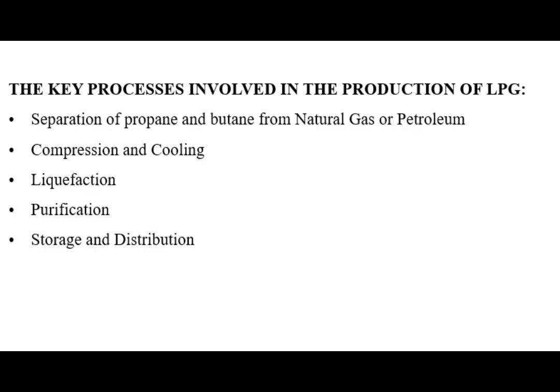7.2.1.3 Liquefaction. As the compressed and cooled gas mixture is further processed, the propane and butane are liquefied under pressure. The real gas behavior of these hydrocarbons is critical in this step, as their properties dictate the conditions required for liquefaction.